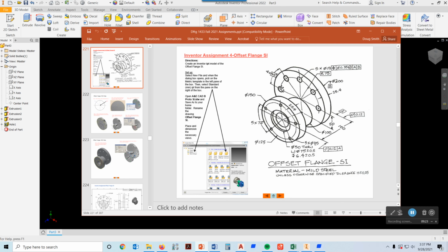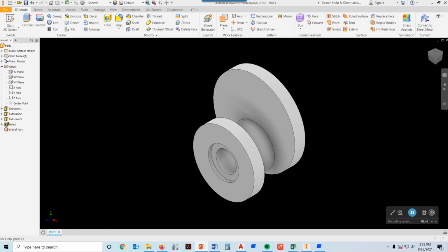I mean, that's the normal direction for it. So what I'm going to do is draw this hole here first. I'm going to place that hole with a diameter of 19, and then I'm going to use the circular pattern, and I'm going to create 5 copies of that, and I'll want that to fill 180 degrees, so it will only go around the top half of my part.